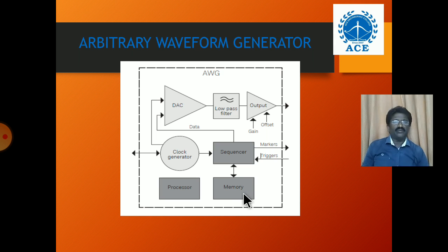The size of the memory will dictate the amount of signal playback time available. So the rule of thumb to determine the playback time is memory depth divided by the sample rate equals playback time. The faster your sample rate, the quicker you will use the available memory.